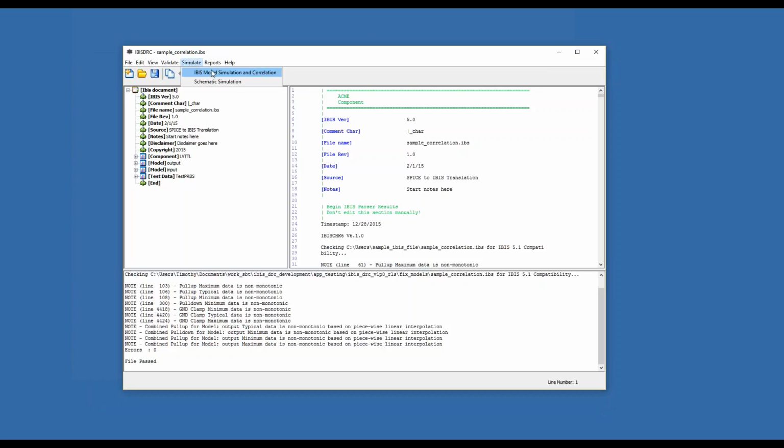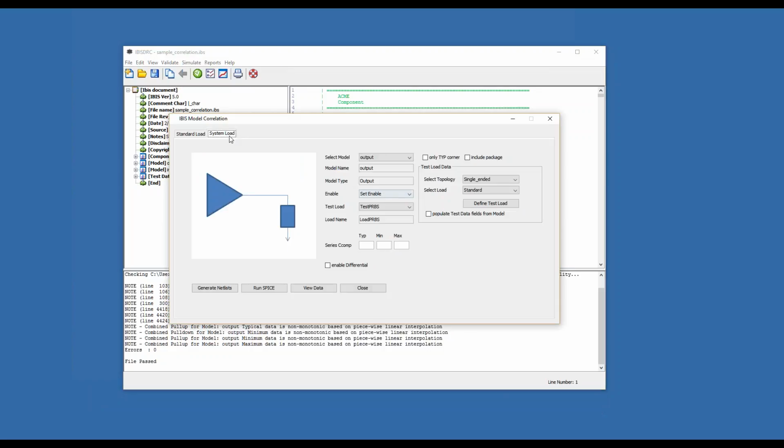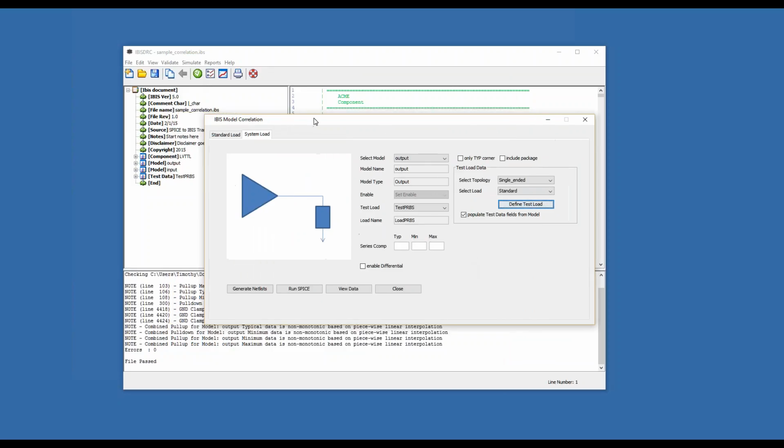And the last thing, again, is really the simulation piece. You really want to simulate this and determine whether this is going to be a problem or not. And what I'm going to show you last is this sample model where there's this test data keyword in IBIS, and you can load in essentially waveforms from anything. This is a great place to put correlation data. So what I'm doing in the tool is I'm using the same test load that the SPICE model is used in. I'm going to run the IBIS model in it.